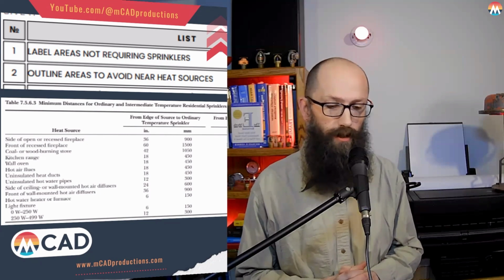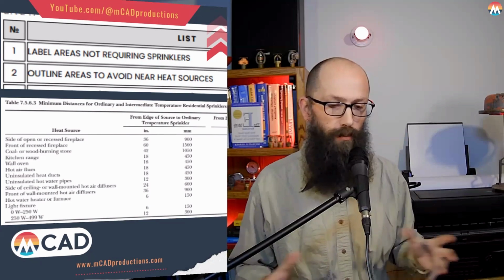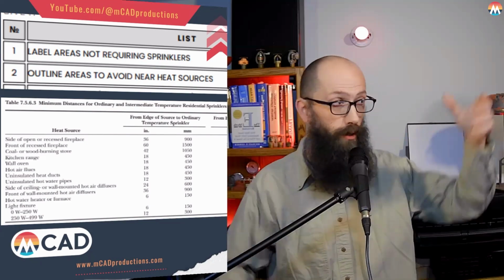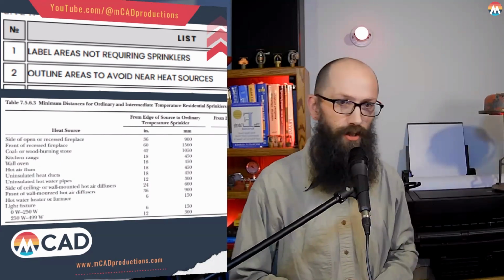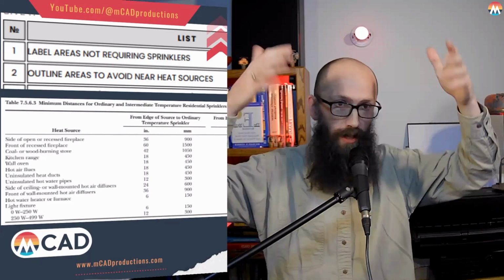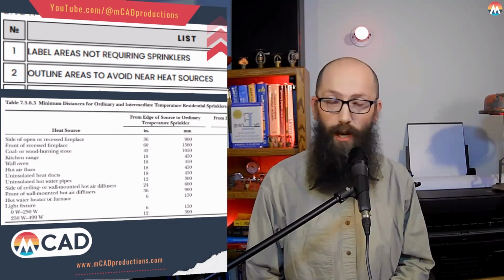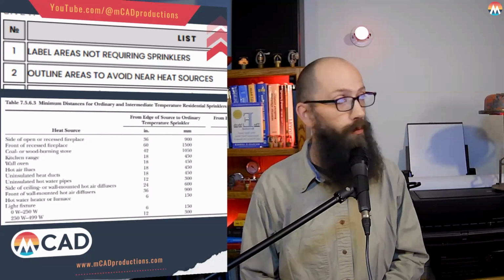So just talking about basically, you can separate a room if you need to make a room smaller, like if you don't have enough water to supply multiple sprinklers. You can divide up a room so it can be covered by individual sprinklers with lintels coming down 18 inches from the ceiling, and you just build them out of framing and then wrap them with sheetrock, is all that's required. But I've actually been involved in projects where we solved problems like that.